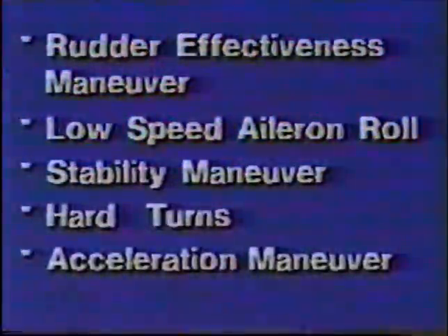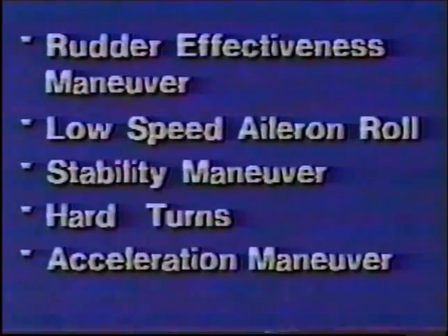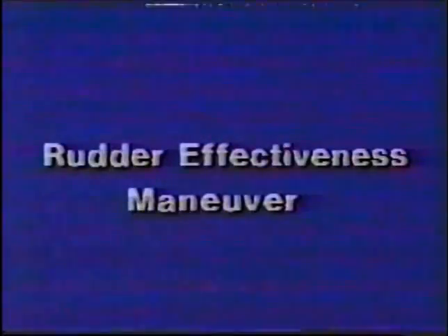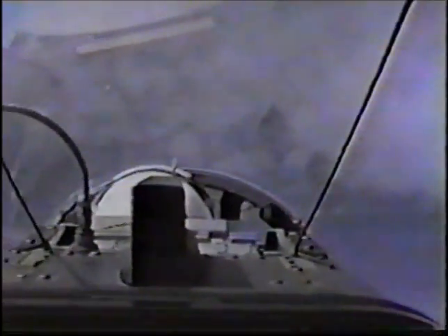At each of the flight characteristic maneuvers, we'll address the parameters and some instructional techniques. Bear in mind, we're not going to talk about all of the possible techniques, just a few to prime the pump. When performing all these maneuvers, keep your eyes out of the cockpit and clear. When performing the rudder effectiveness maneuver, remind your students that with the rudder deflected, the unsymmetric G limits apply.